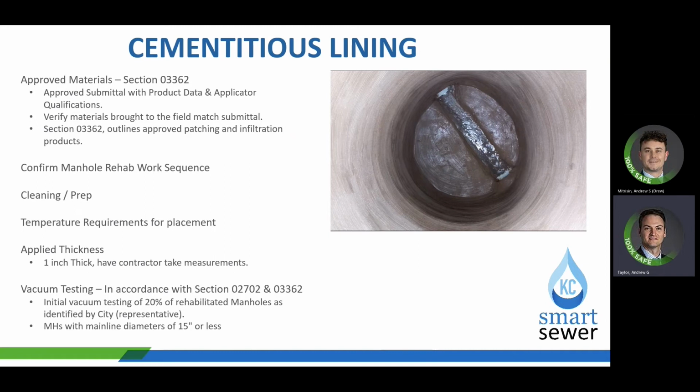And then vacuum testing, do this in accordance with the 2702 and 3362 specification. So, the city representative should identify 20% of the line manholes for testing. These manholes will be selected on segments that have pipe diameters of 15 inches or less. So keep that in mind during the selection process. I know that the specification reads that the city should select these manholes, but we are okay with the engineer selecting these manholes and providing those to the contractor to be tested.